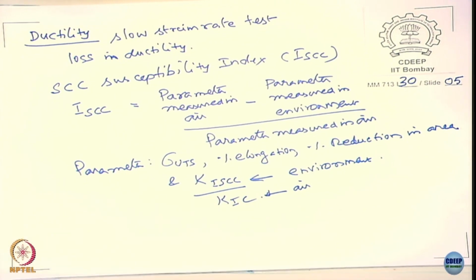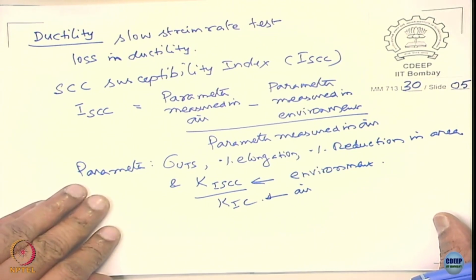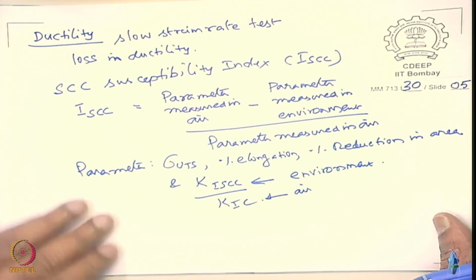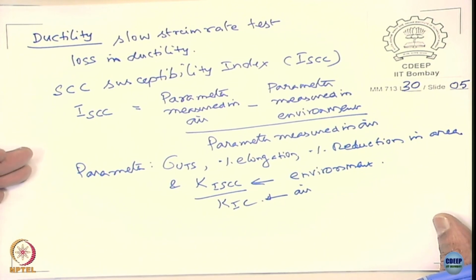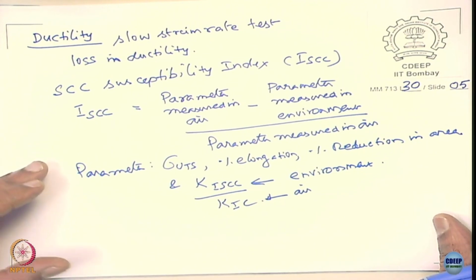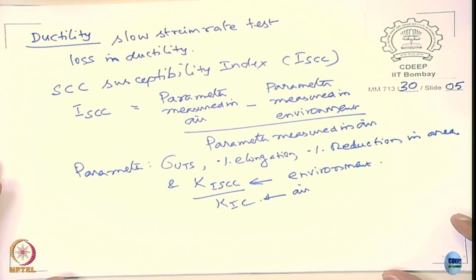We saw this briefly. From the fracture features, if you can recollect, we said yes, this is brittle, and we also said that in a failed sample in SCC, whether you do it in a laboratory test or in the field, you also have a ductile fracture component in the specimen.